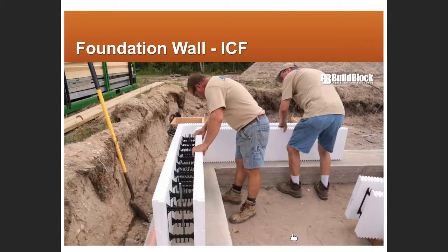Thank you. Right, remember, concrete reaches its ultimate strength in 28 days or so, right? You don't wait 28 days to strike the forms. You're going to strike the forms within a day or two. But let's say you're building a high-rise building or a parking garage, you're going to strike the forms and keep moving upward, but you're not going to drive cars into that parking garage until the concrete has reached its full strength.